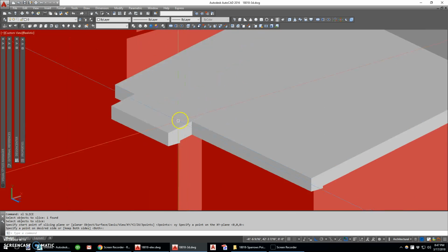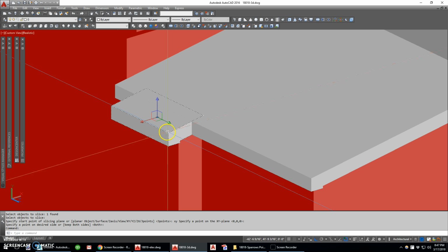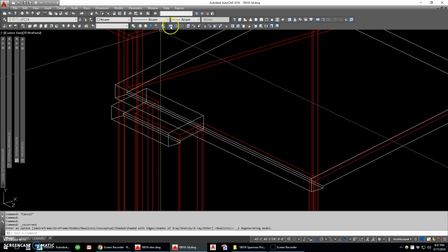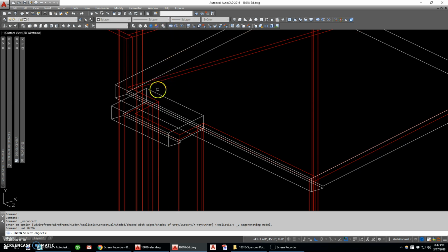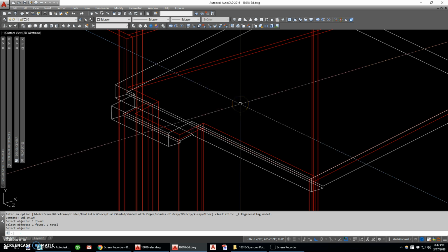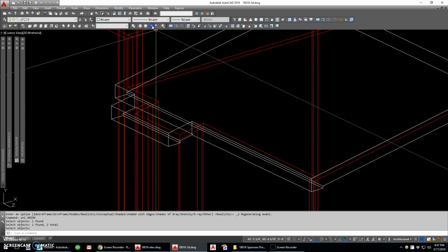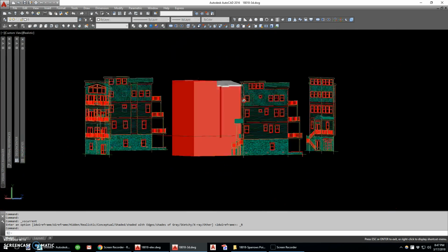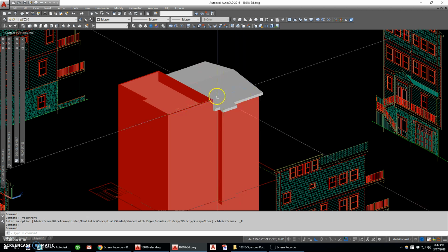Now when I go look at this, bam, it looks great. However, the geometry is sort of intersecting this geometry. So what I'm going to do is use my union command, which takes two solids and makes them one, whether they're connected or not. Looks funny, but if I view it in 3D and zoom, I'm going to pull back and kind of zoom around, it looks right. Great. Back roof is done.